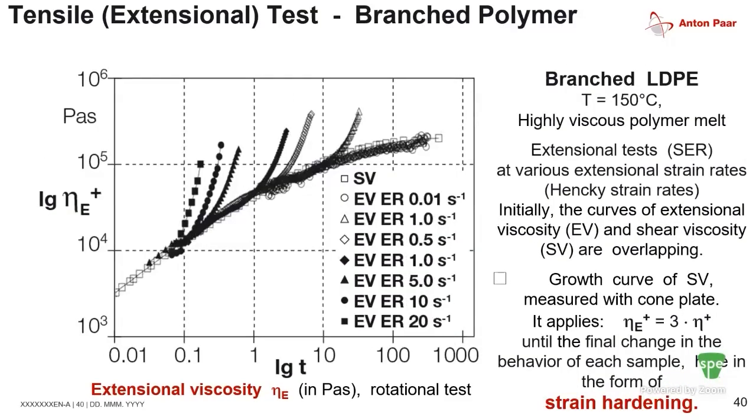However, in low density polyethylene, or LDPE, we see a completely different response. As we go to longer and longer times at these set held rates, we see an increase in the extensional viscosity. This is because as we pull it in the extensional direction, the sample starts to align with the flow field, and we have what we call strain hardening.